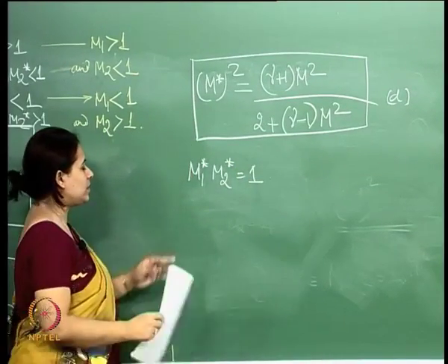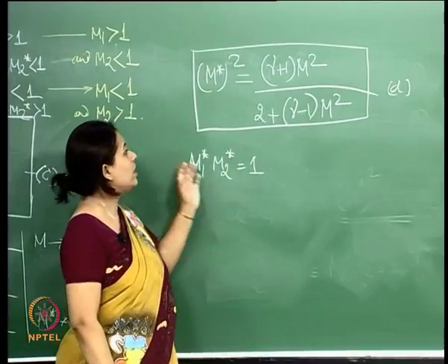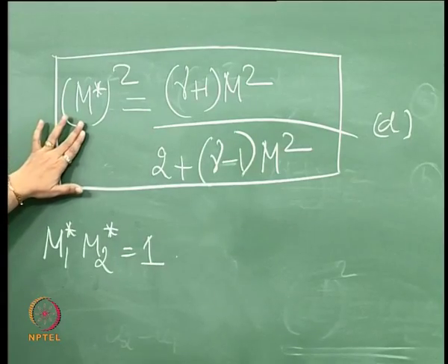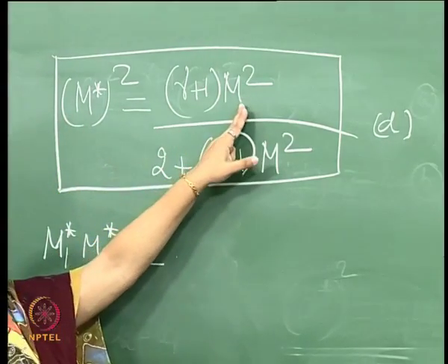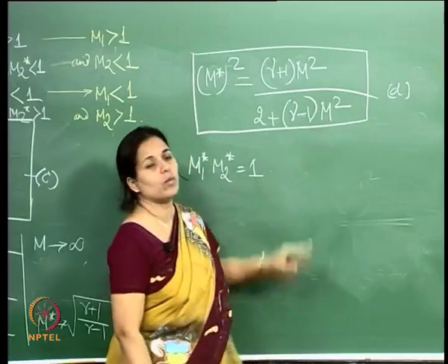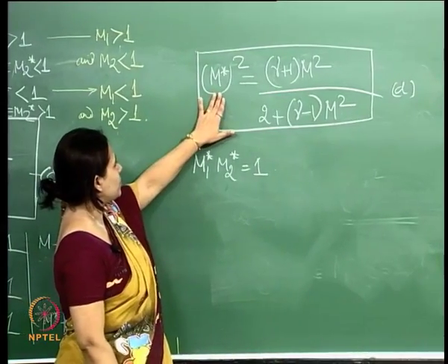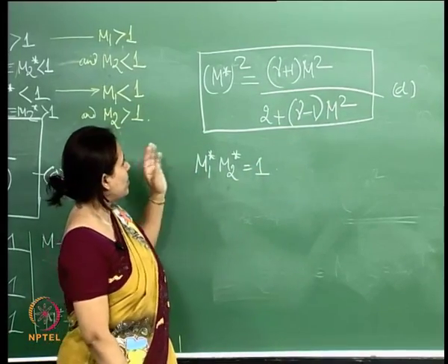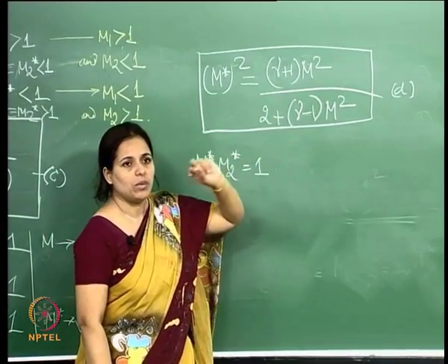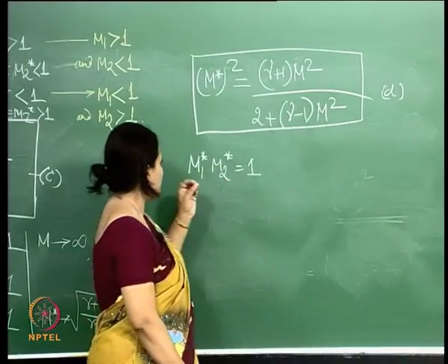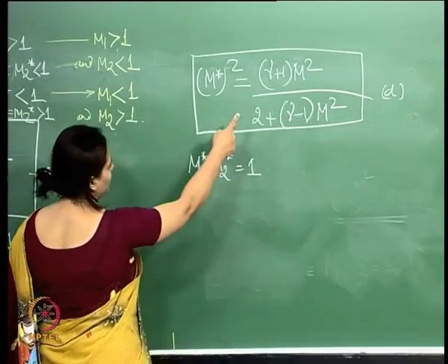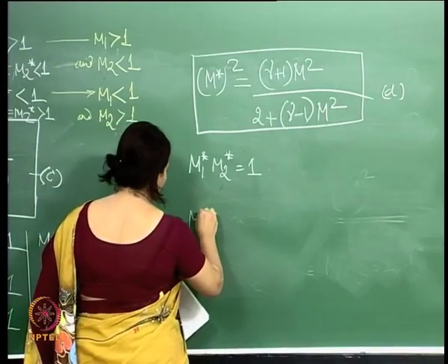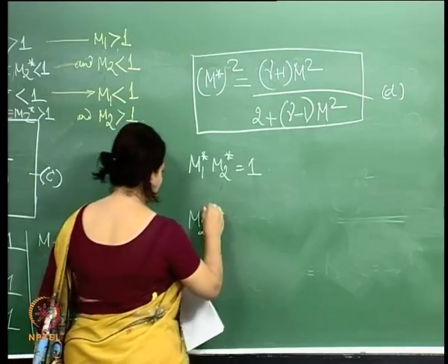Right. This is the Prandtl-Meyer equation. So, let us introduce this into this, meaning if I say M1 star, then what I get is M1 and M1 over here, and if this is M2 star, then what I get over here is M2 and M2 over here. So, what I am able to do here is introduce the Mach numbers in regions 1 and 2. Once I do that, let me bring that up into here. So, what I get is this, then I rewrite that.